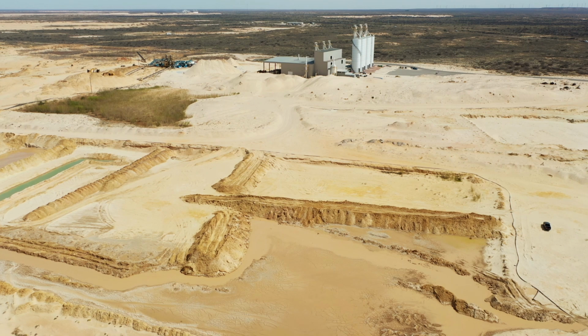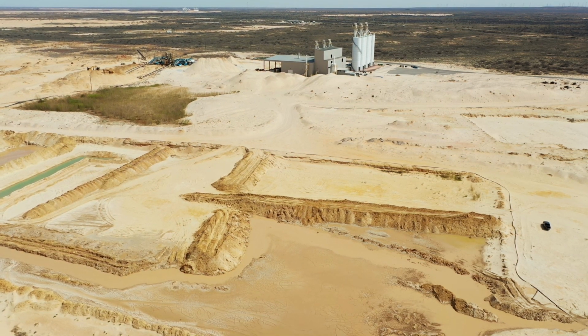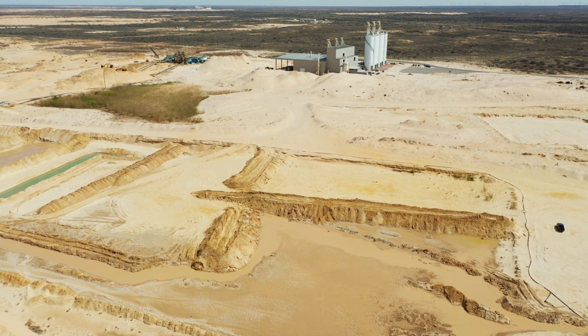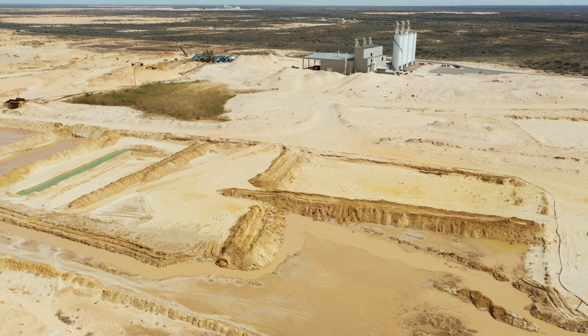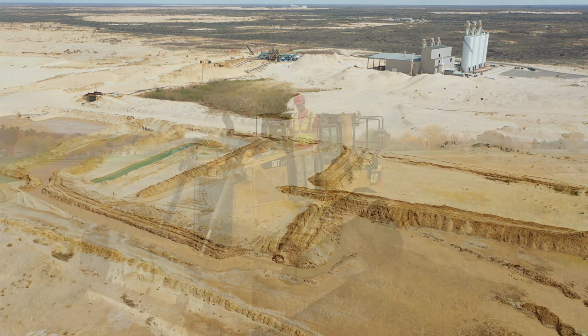Berms shall be constructed at a minimum height which is equivalent to mid-axle height of the largest vehicle or equipment operating in that area or road. Berms shall be made of substantial materials and inspected throughout the day.